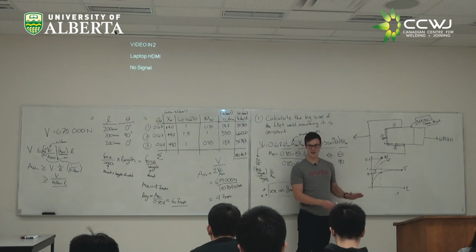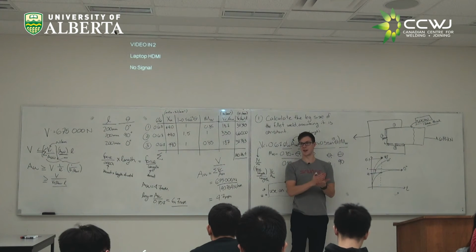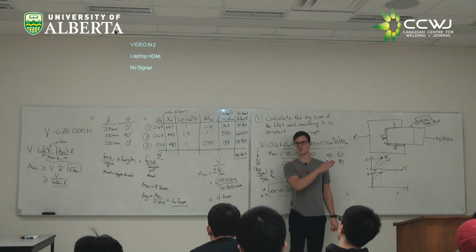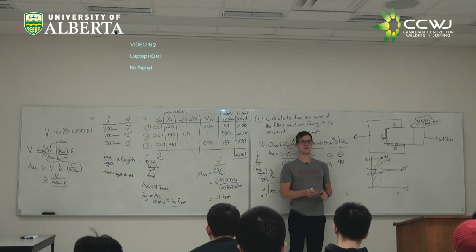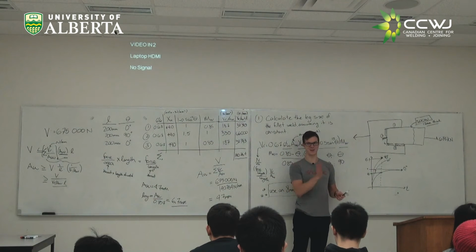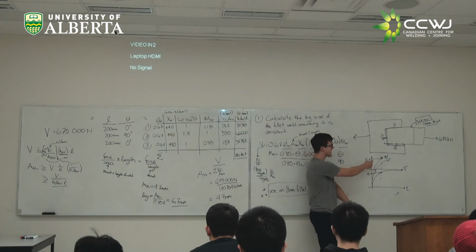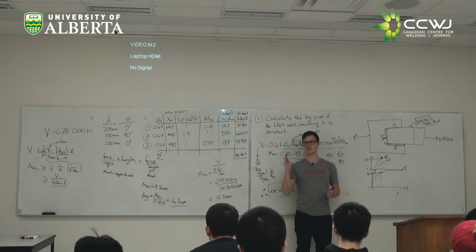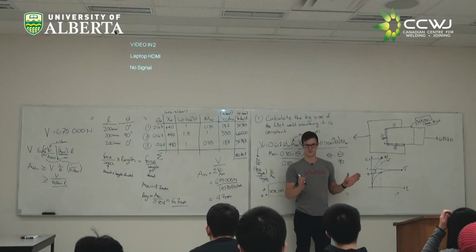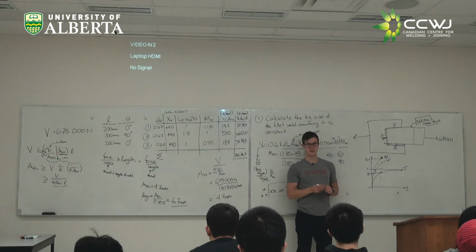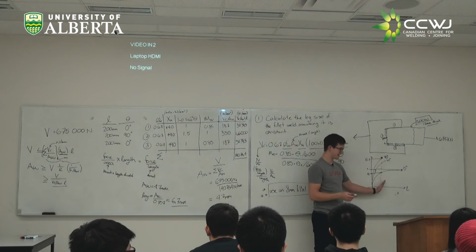All we're saying here is when any part of the weld has reached the strain at which it would fracture, we're going to consider the whole structure to have failed. That's our failure point. We're going to design so we never reach that point. I think that comes into the concept of limit states design. I'm not a civil engineer, so I'm not going to try to explain what that is to you guys. But it's essentially saying we never want to reach a point where any of our weld has exceeded the strain at which it fails.